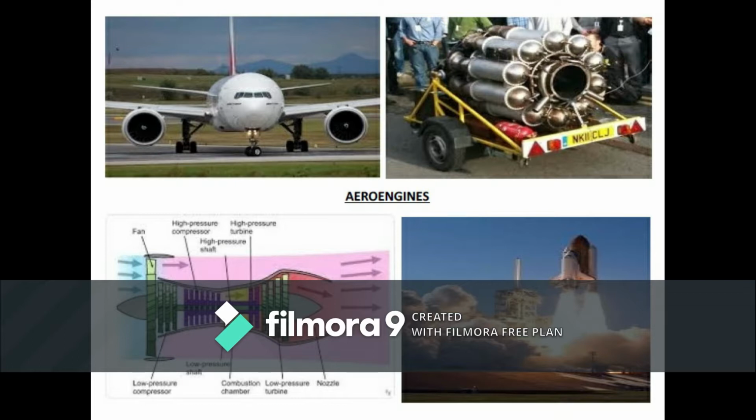So the crankshaft is responsible for conversion of reciprocating motion to rotary motion, and the rotary motion is transferred to the propeller, which is fitted in front of the engine itself, with direct drive from the crankshaft. Okay, in a jet engine we do have some reduction gear mechanism, which I will explain later, but in a piston engine it is almost all direct drive. It is given to the propeller, and the propeller starts rotating.